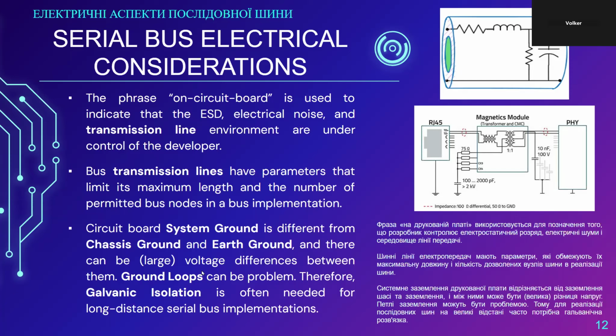However, if you're connecting earth ground, for example on the shield of a signal cable, and route that to a different room in the same building, and that room has a different voltage potential on that earth ground, you might get fairly large voltage differences between the different earth grounds.